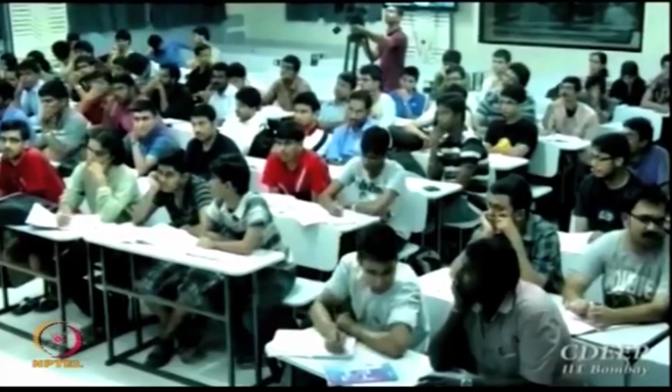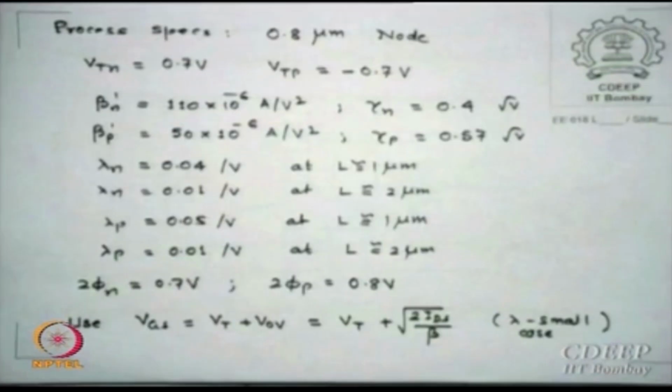Okay, analog circuits always, unless a single ended power supply requirement comes, some op-amps do say only one, otherwise you must see all op-amps show 2 terminals, that is the idea. All general purpose op-amps will have VDD and VSS. Only op-amps with specific requirements may use a single ended power supply. Okay. These are the 0.8 micron node specs taken from a SPICE file.